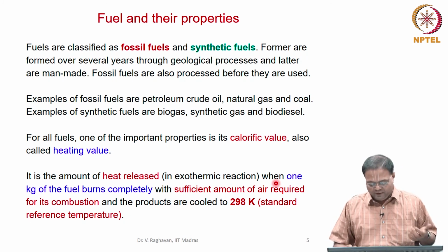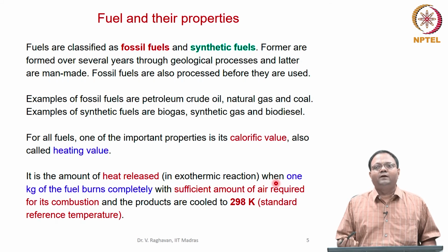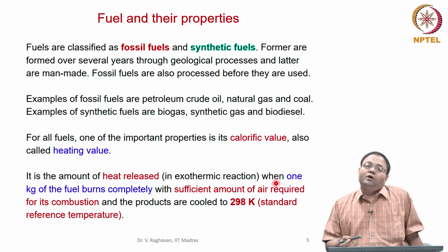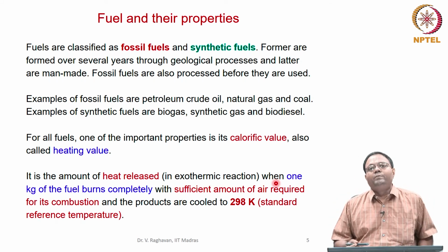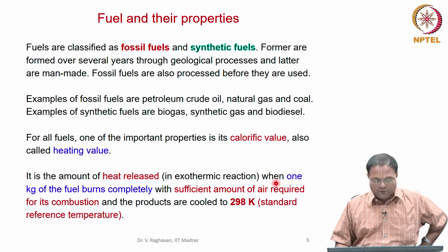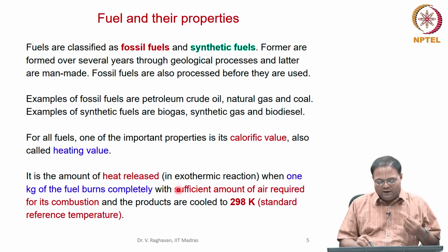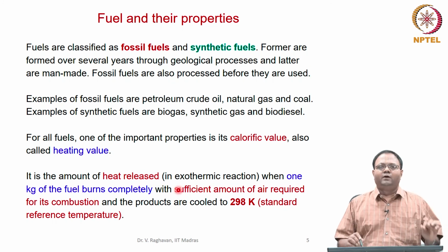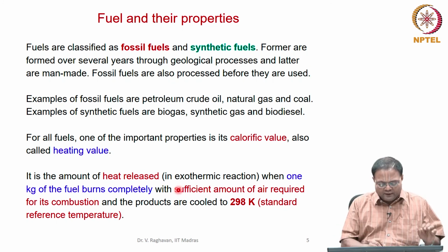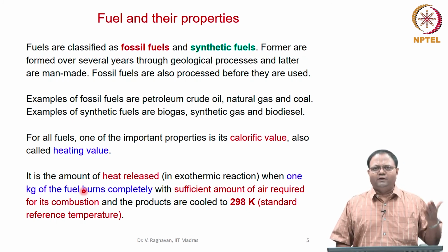When I say completely, it's only my wish, but I do not know whether I can normally burn anything completely. It is not easy to burn everything completely, especially with solid fuels. There are a lot of challenges in burning them because of the heterogeneity of the fuel, especially with the ash content and so on. But what we envisage here is: when you completely burn it, what is the heat released when you burn 1 kg of fuel? That is defined as the calorific value, a theoretical value.